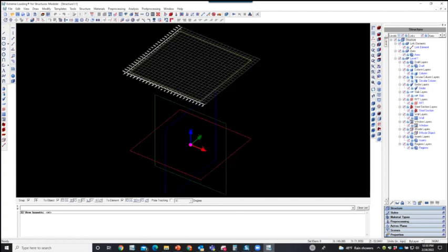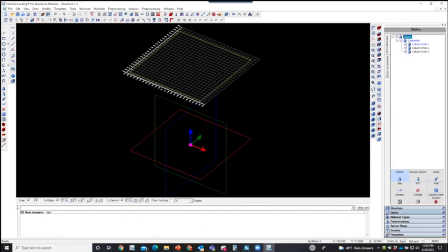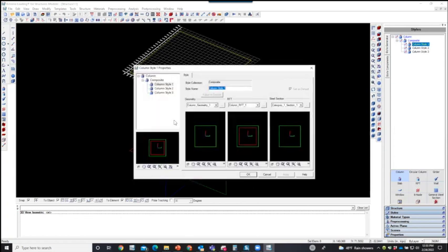I will first begin here with assigning the style of the column. So the technology here allows the engineer to model components rather than element by element. Usually, when engineers use high fidelity numerical modeling like ANSYS or LS-DYNA, they have to model element by element. Here we model component by component, and then we subdivide this component into elements.